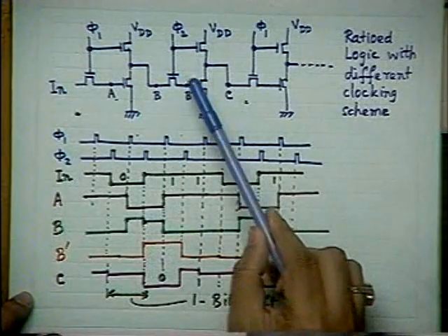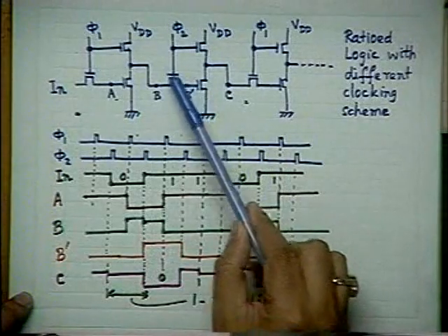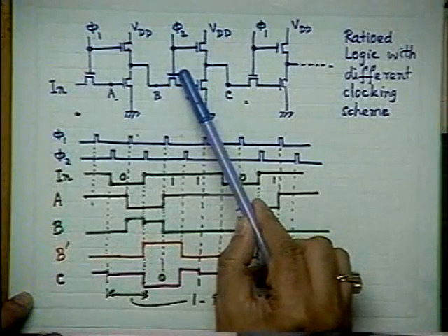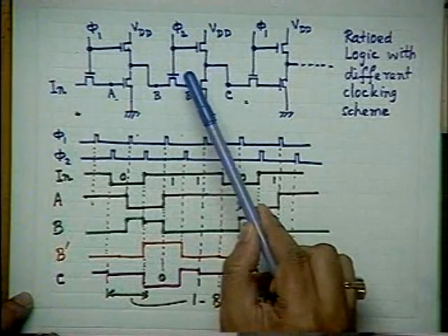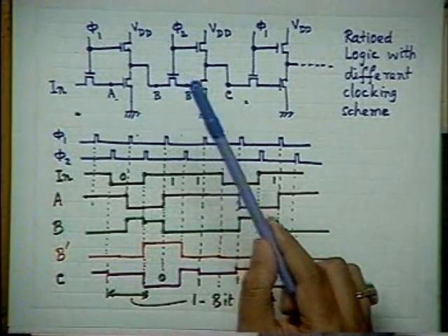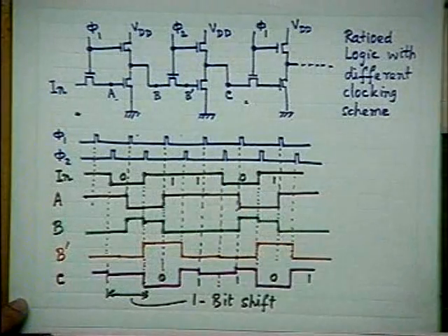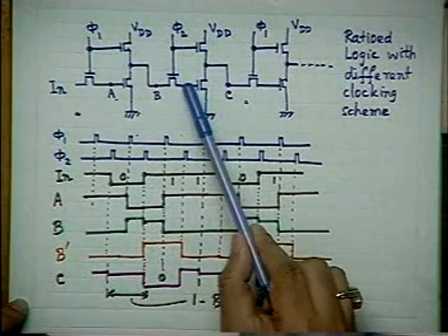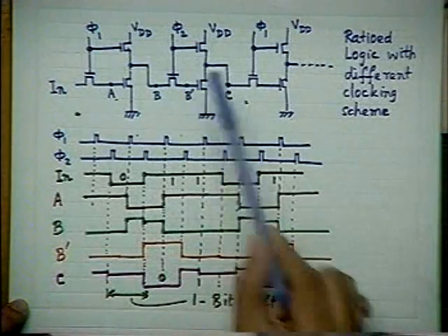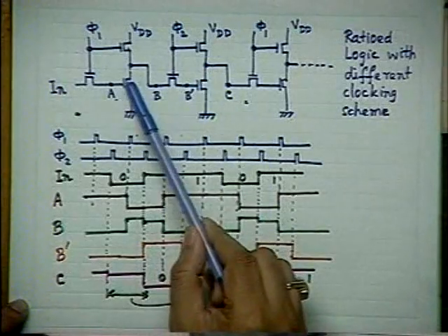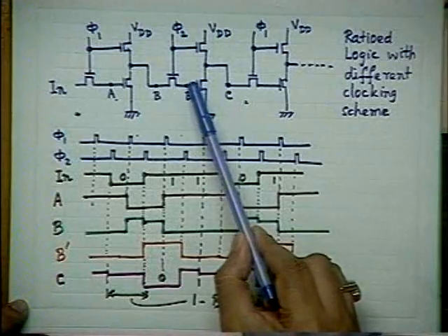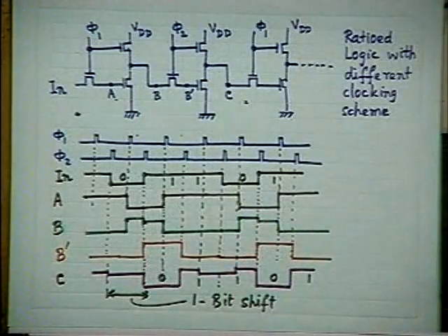Now please see what the effective capacitances are when this is off, meaning drain bias may be there, but the gate bias here is 0 or less than threshold voltage. That is how we call it an off transistor. At this point, therefore, there is a MOS capacitance between the gate and substrate of this transistor, substrate and source. Please remember, all the substrate is shorted to ground. So between the source substrate and the gate, there is a capacitance, which is the MOS capacitance.